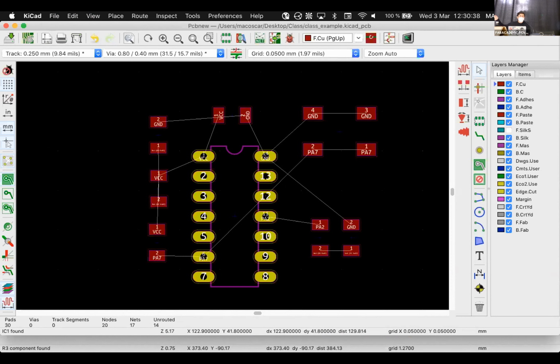Imagine how we manufactured these past weeks: we used an end mill that is removing copper from the PCB. We want the components separated enough from one another so that the end mill can go through. Otherwise, we cannot make the traces, or we cannot actually make our circuit.